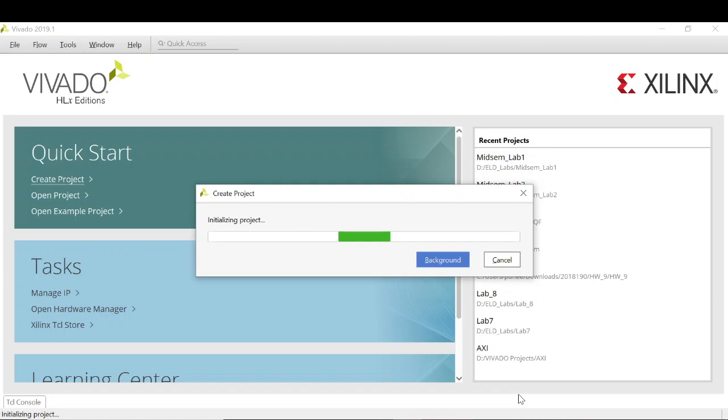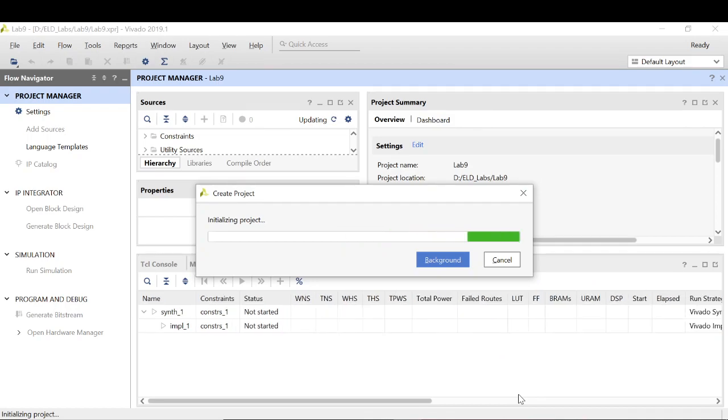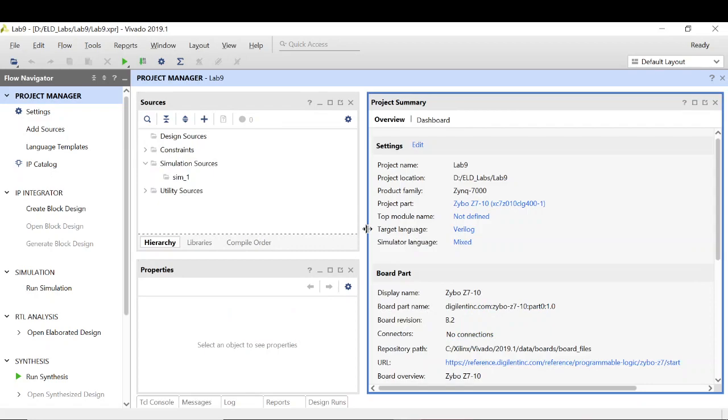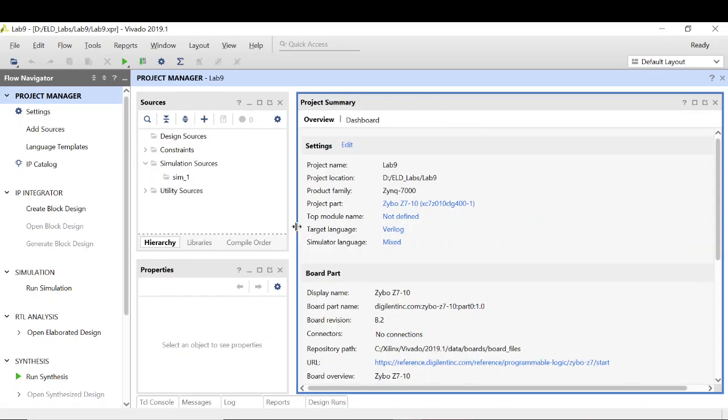The very first part in the design flow for this hardware software co-design is to create a block design, which is also task one of this lab. So we'll look into how to create a block design. We will create a very basic block design today. We are not including the hardware part, the FPGA part. We will simply program the PS and write simple applications on it. That simply means I only need the Zynq processing system, right? So let's see how to do that.